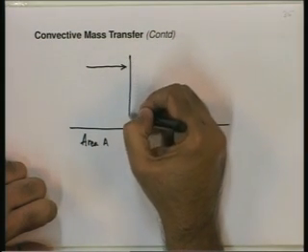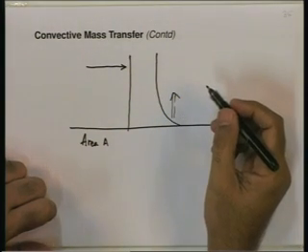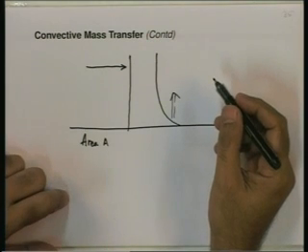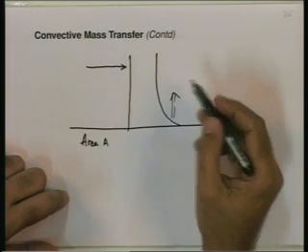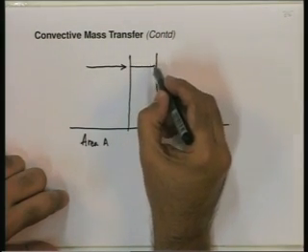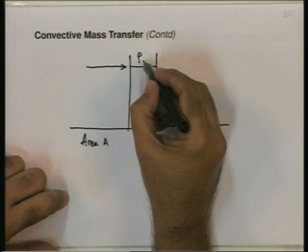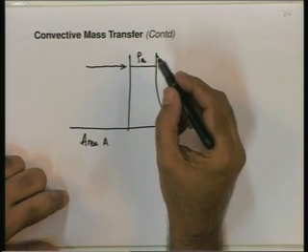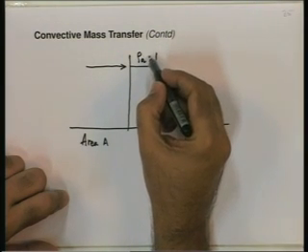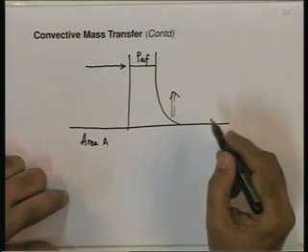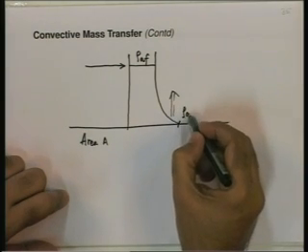And it is getting transported because if we plot the density difference for the fraction or component A, we will find that far away from the wall, the density of component A per kg of A per unit volume will be, say, rho AF, whereas at the wall it will be rho A wall.